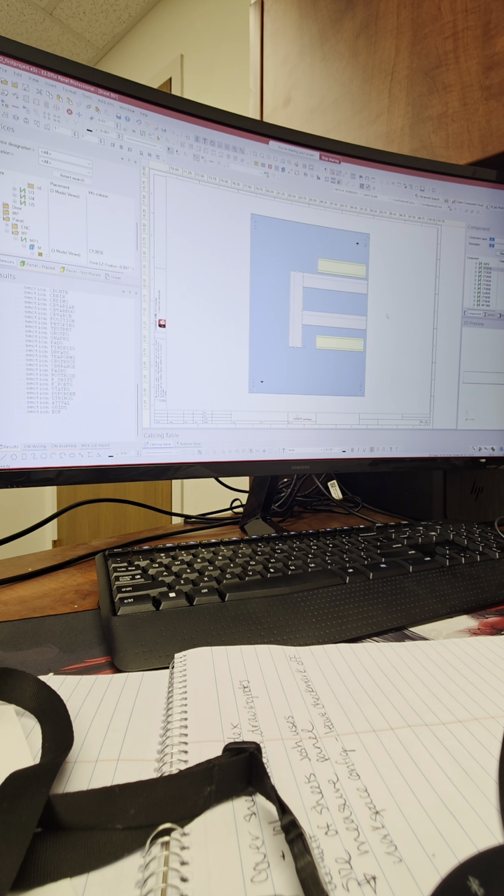Right? But if you say, all right, I'm not going to use ducts in my project, as I don't need to see them, there are two things you can do. It's a workaround purely from a visual perspective, but it's a requirement for this automatic routing that takes place in this tool. These ducts have to be there just to route the wires from object A to object B. But from your perspective, you don't want to see it and you don't want to see it on your BOM, right? That's kind of your two requirements.